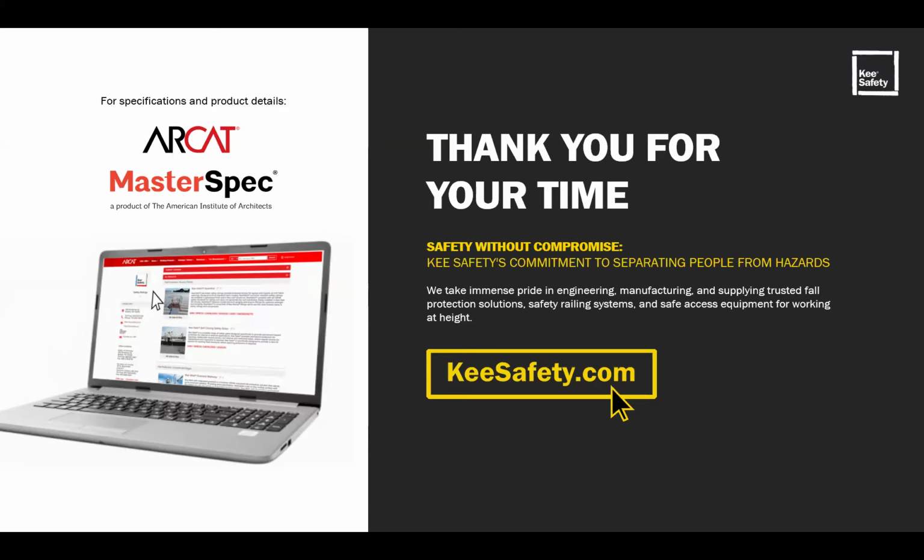First one asks, can you go a little bit more into the requirement for inspections of your fall protection? They're struggling with finding vendors to inspect the different fall protection systems on the roofs each year. Good. That's a very good question. So it depends on the system that you integrate, right? If you have an active system, meaning it's an anchor point or a lifeline, that needs to be inspected every single year by the person who installed it, ideally, or a competent person who has been trained by the manufacturer of that system to inspect it.